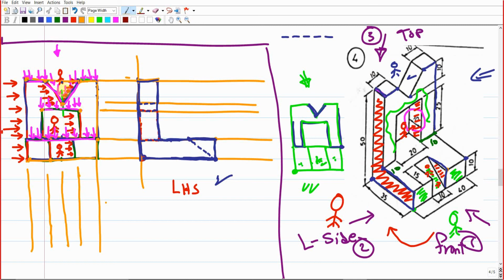top view. Then you're gonna keep the same distance as you kept between the front and the side view. So I'm gonna keep this distance, the same one, and draw a horizontal line. So the top view should start from this line going down, this direction. It means that all of this area should be the top view of this shape. But as you can see, we end up with two start points. This point is on the top right corner of the top view, and this point on the left top corner of the top view. You can start from either one.